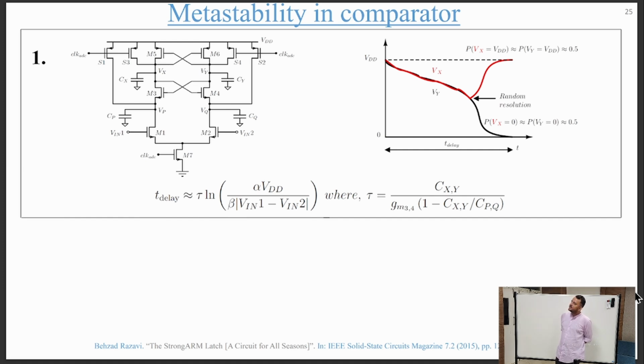Also, metastability can be induced in the comparators, all the comparators used in our flash ADC. If the sample of Y[n] falls near the threshold value of those comparators, it can go into metastability, and it gets randomly resolved based on the virtue of events at those nodes.